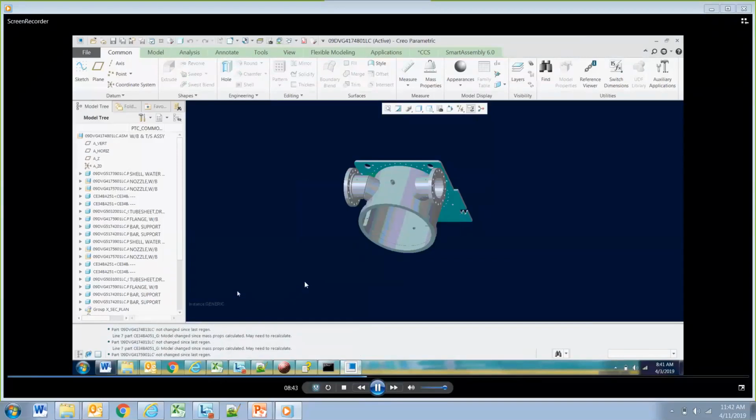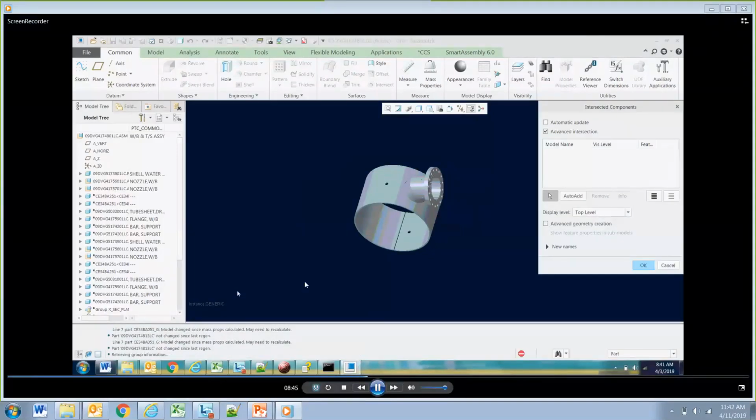The reason I did that was because I was seeing a little bit of issue with my code. If the assembly level features that are now being created were created before the family table, it would error. So I chose to create the full family table and then roll the model back. As you see, many of the items in my assembly are now suppressed because it's been rolled back, and create the feature after rather than before the family table.